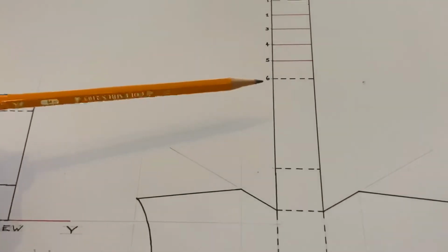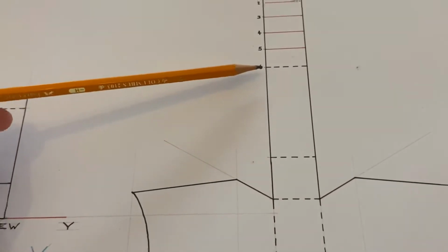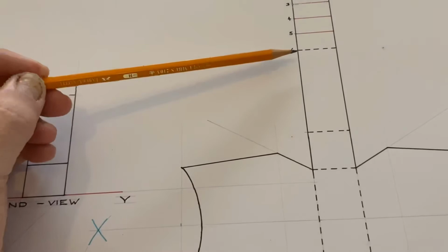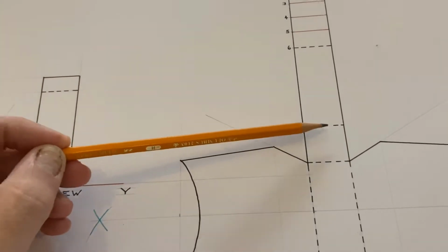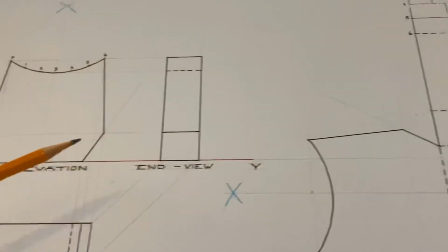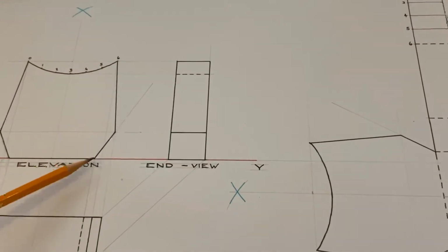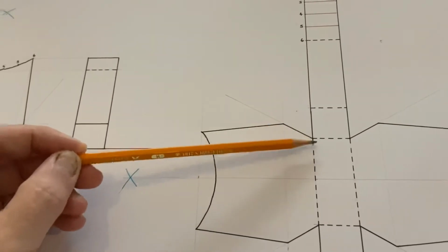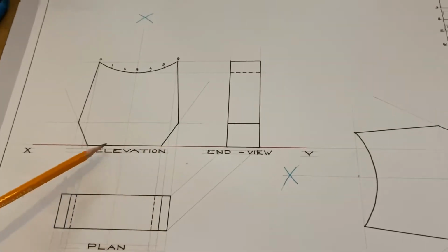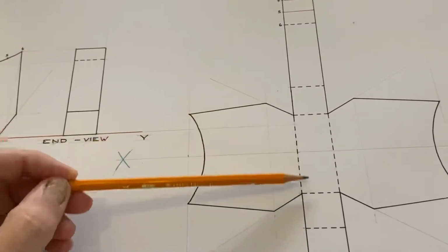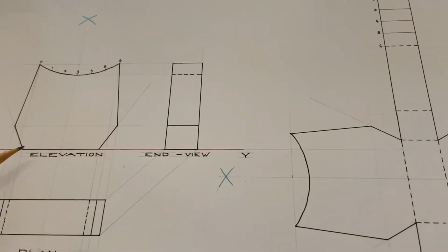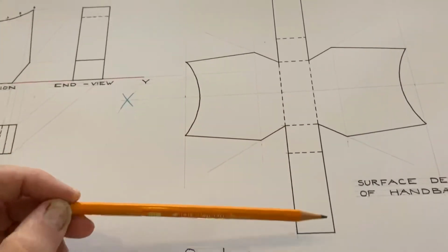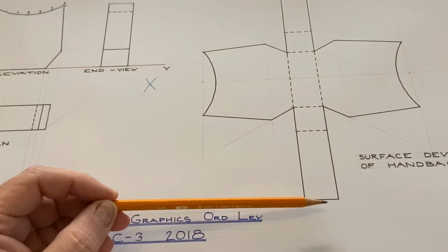So, going back to our surface development, if we take the distance there of the long side and we mark it from position 6 into here, that will give us the length of that surface. Then we take the distance from here to here and we mark that distance down there, and that will give us that sloping side there. Then we take the distance across the bottom and we mark that distance there, and then going back up the other side, we take the distance from there and back up, and you mark those two distances there, and that then will give us the end of the development.